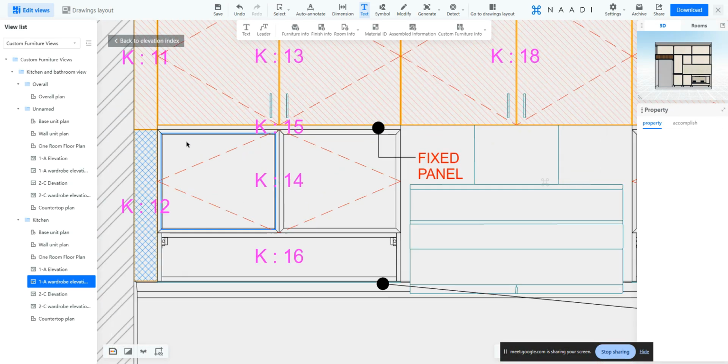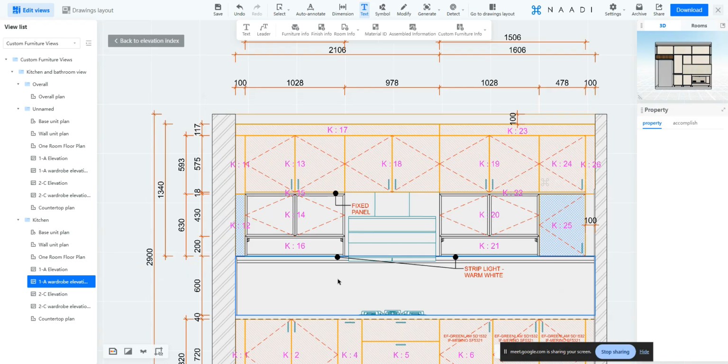Apart from that, this one is a profile shutter, right? Your aluminum profile shutters. In some cases where organizations even have a practice of adding one solid finish, a black or a gray color to mention the aluminum profiles, right? In those cases also, you can just do that. Okay, but the thing is, initially you can't directly select that profile. It will select that entire shutter. Okay, so in those cases, what could be done? Because only if I select that profile, I'll be able to apply an edge for it. If I select that entire profile shutter, including the glass, the same edge will be applied. In those cases, then how can I micro select that profile alone, not the glass of the profile shutter?